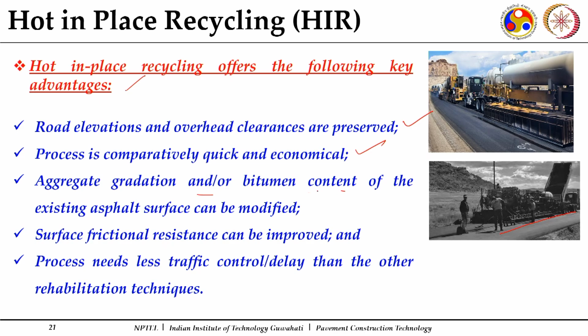The aggregate gradation or bitumen content of the existing asphalt surface can be slightly modified, because depending upon the requirements we can modify the aggregate gradation as well as the asphalt content. Surface friction also improves, because with the modification in the aggregate gradation we can definitely achieve a surface with a higher amount of skid resistance.